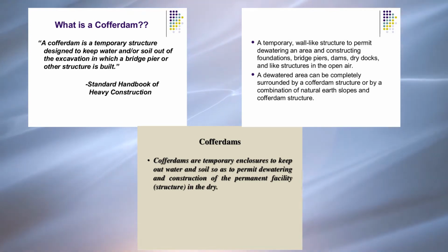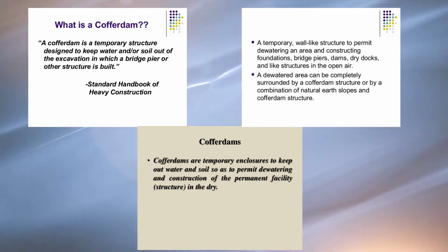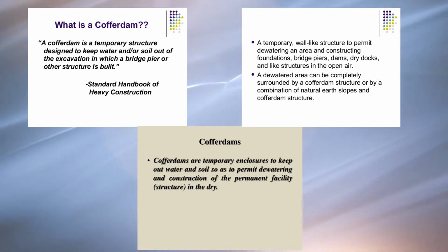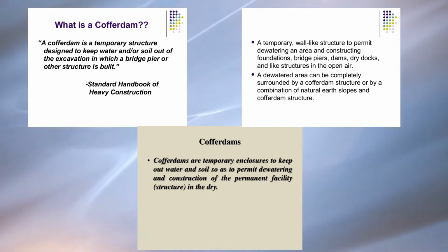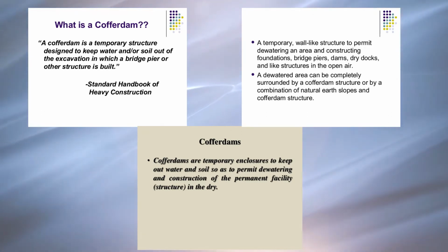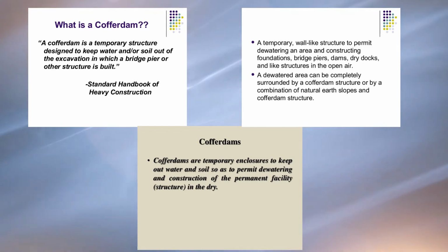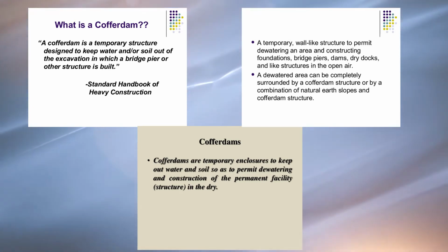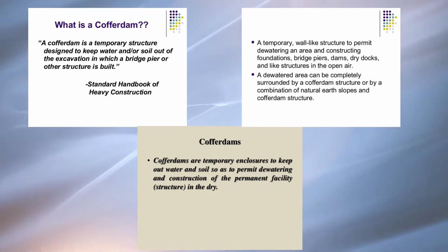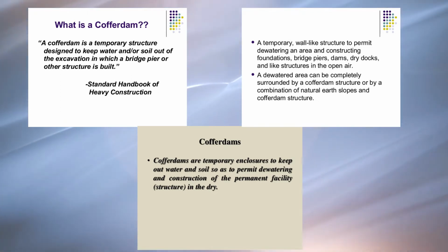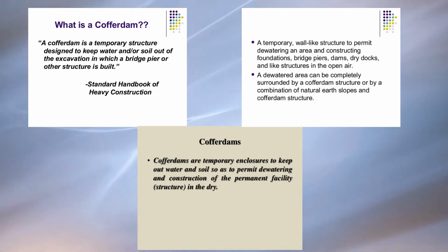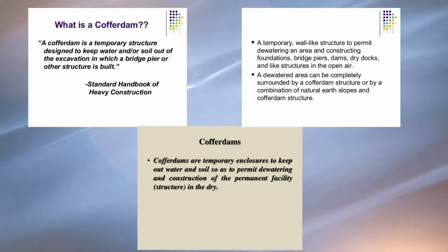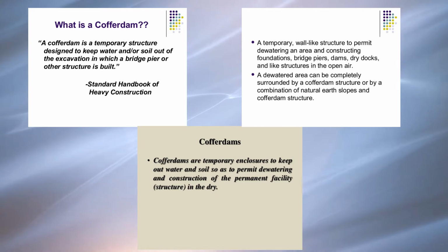What is a cofferdam? Cofferdams are temporary structures used where construction is being carried out in areas submerged in water. They are most commonly used to facilitate the construction or repair of dams, piers, and bridges. The aim of a cofferdam is to be as watertight as possible to create a dry area in which to complete the required building works, or at least to limit water ingress to a safe level that can be pumped away.